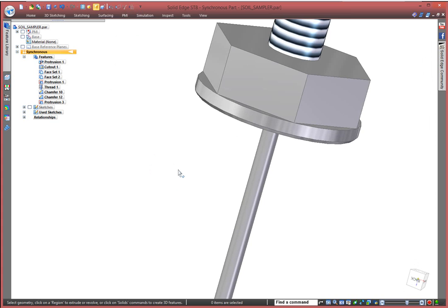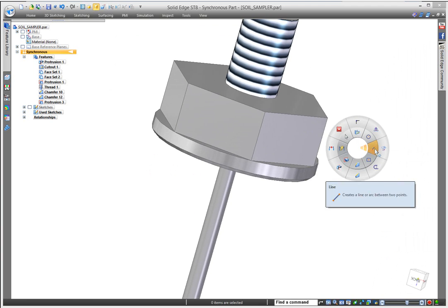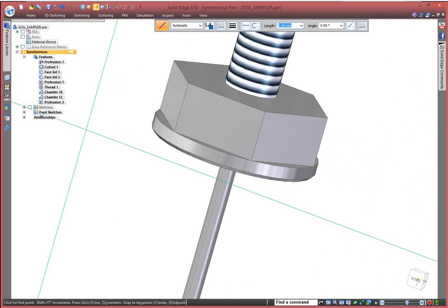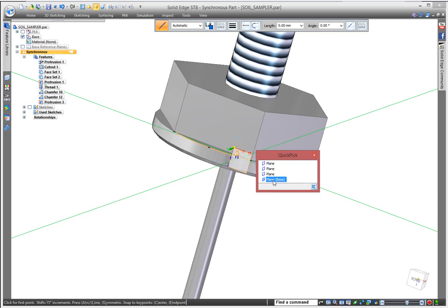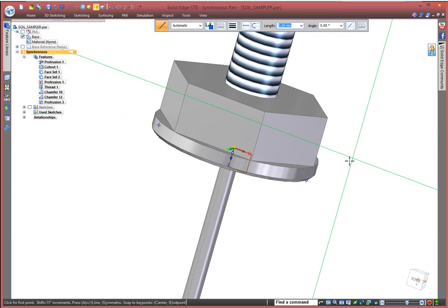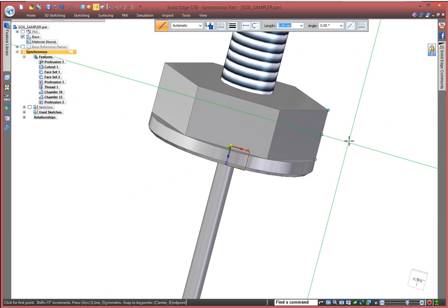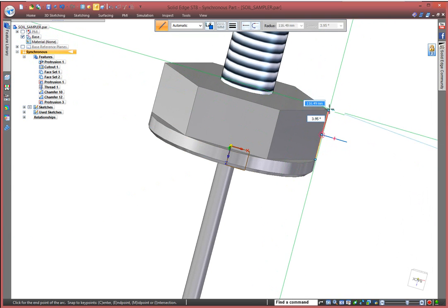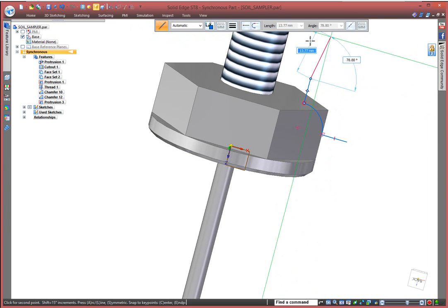Now Solid Edge allows us to create complex features from simple sketches very simply. I'm going to use just our simple sketching tool here and define the plane on which we want to draw. Again, there's a number of planes in there. We use Quick Pick to find our base plane and lock to that, and I'm going to not draw yet. I'm going to draw into here, just create a line into here, an arc up from here to the .90 point, and just up here.